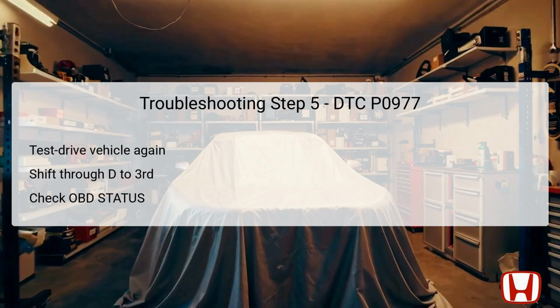You'll need to conduct another test drive after the clicking sound is confirmed. Ensure the shift lever remains in the D position, repeating the same process of shifting from the first through third gears, and maintaining the vehicle in third gear for at least 1 second. This test drive allows you to monitor the performance of the shift solenoid valve after confirming that it was operational.